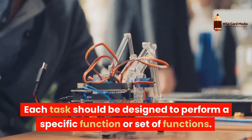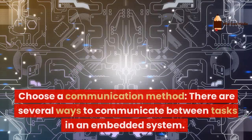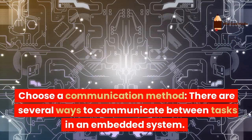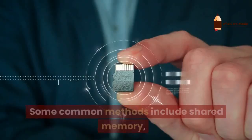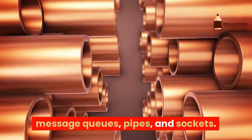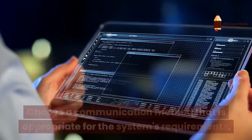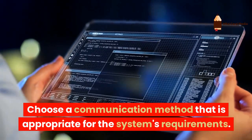Each task should be designed to perform a specific function or set of functions. Choose a communication method. There are several ways to communicate between tasks in an embedded system. Some common methods include shared memory, message queues, pipes, and sockets. Choose a communication method that is appropriate for the system's requirements.